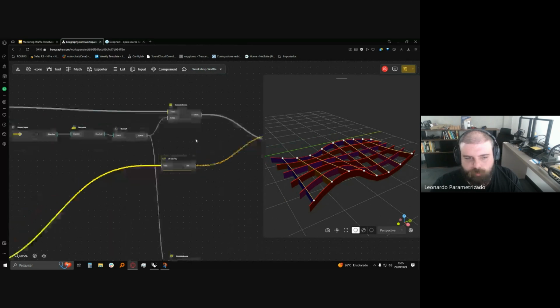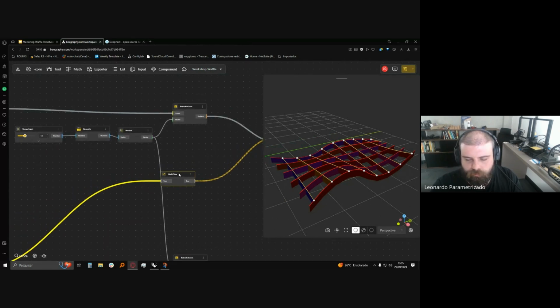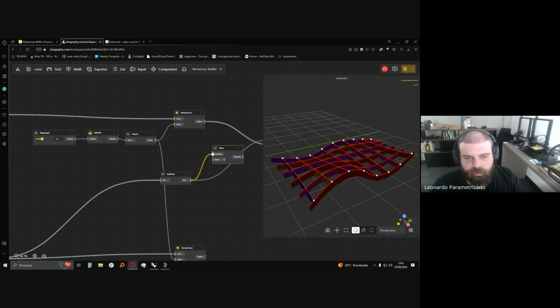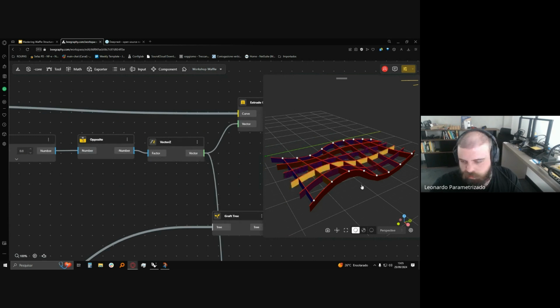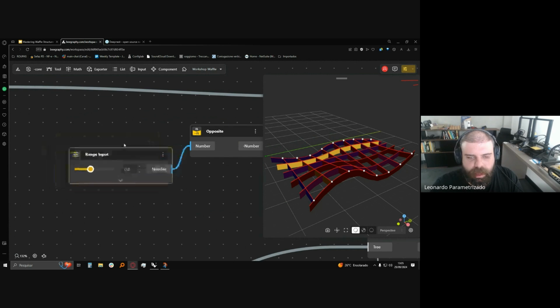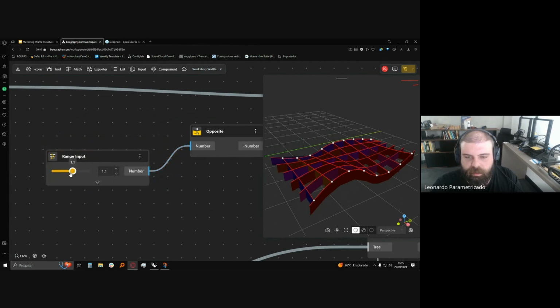So what we'll be doing, just take this list, I'll be moving this geometry in Z negative because it's downwards, and it's exactly half of this value here. This value indicates the height for each one of our beams.